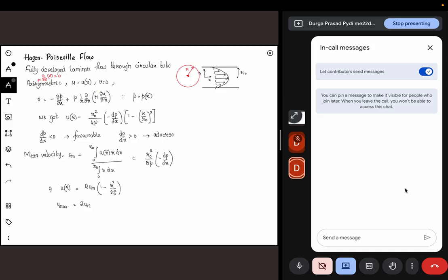Here again, we have two different cases. It is a straightforward one. So we see if the pressure is higher here and lower here. If I say this is P1 and P2, and P1 is greater than P2, then if I take the gradient del P del x, or dp dx, along the x direction pressure is decreasing, so this will be negative. Because P1 is greater than P2, flow will happen from left to right, so this is favorable.